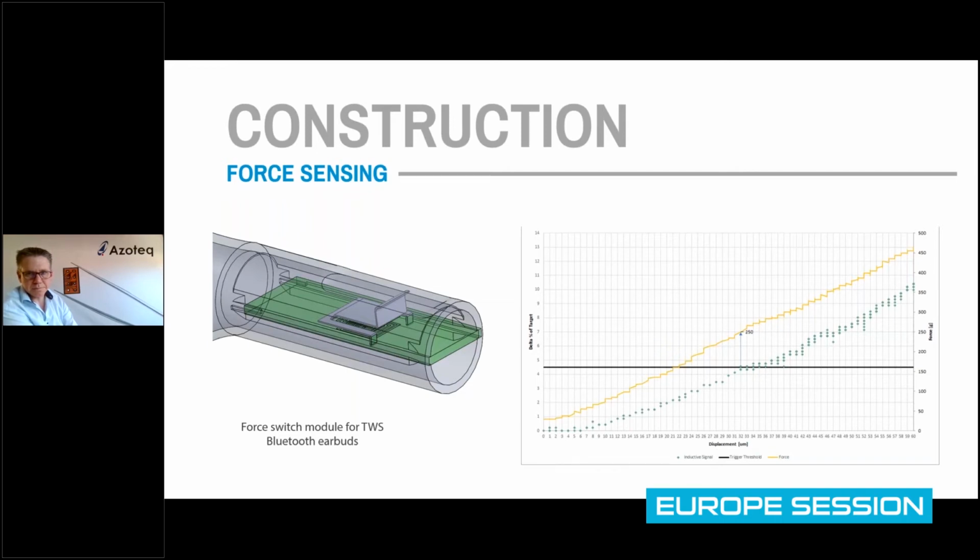Yeah, I see. So in order to detect that change in the current, I guess that you are sending a chain of pulses with a fixed width, and then that voltage is applied to the inductor, and you measure the current. And if the inductor is at the default value, it will measure a specific value of current.